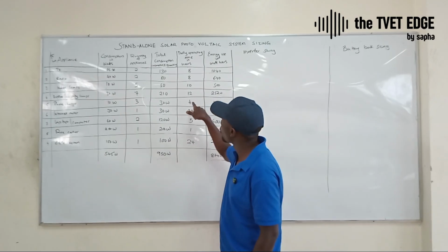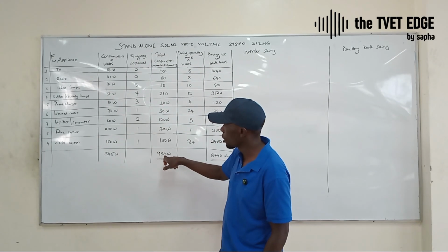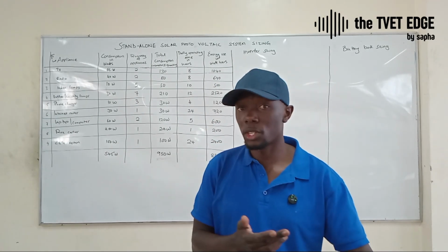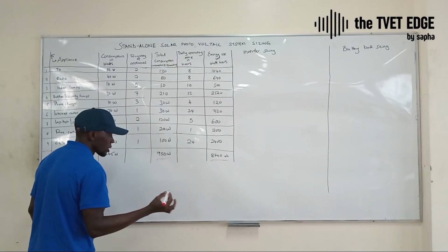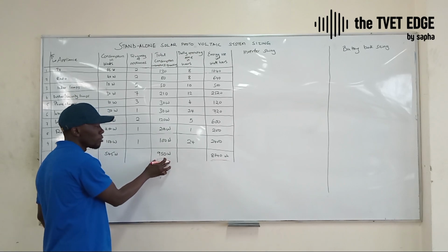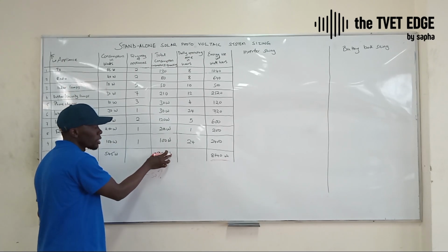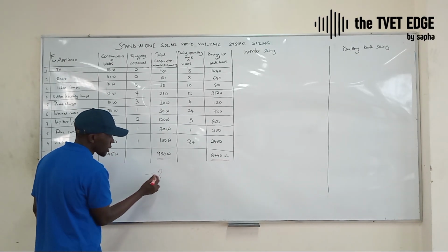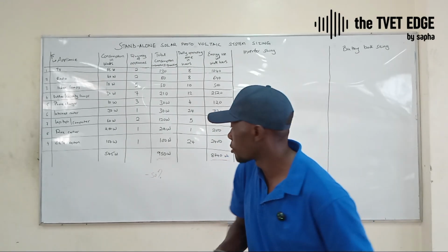That also means the daily operating time might stay the same, 4, but this value will have an effect on the 950 watts. So what normally happens in this case, for a standalone system, we will advise you to introduce a safety margin. In most cases, it's normally 50% of what your system is supposed to deliver. The base value is 950 watts. The safety margin is 50% of 950 watts. If you're fast enough, you can comment before I'm done. All right, that is 475 watts.